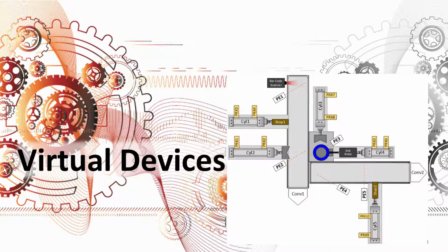So instead, we have to use virtual processes, and virtual processes are made up of virtual devices. Now, the digital field device simulator that I'm using has 6 inputs and 6 outputs. However, the I/O module that I'm using, the combo 6 in, 4 out, is only connected to 6 inputs and 4 outputs.